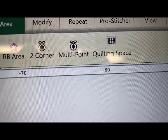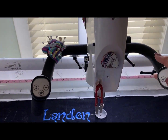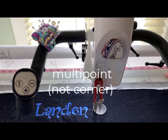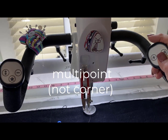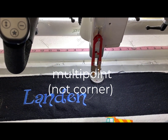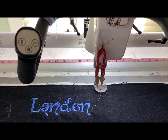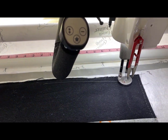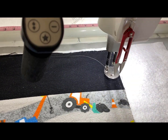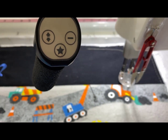To draw my new area box, I go to the area tab, and I could select the 2-corner or the multi-corner, and I selected the multi-corner, which correlates with my diamond shape on my right handlebar. So every time I move my needle, and that moves the crosshairs on my computer, I will select that diamond shape, and that will put a new mark. Now that mark, if I move in the same direction, it will continue the line. If I move in a different direction, it forms the angle. So now I've made 3 angles on my rectangle on my computer.